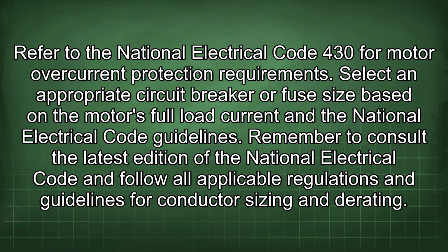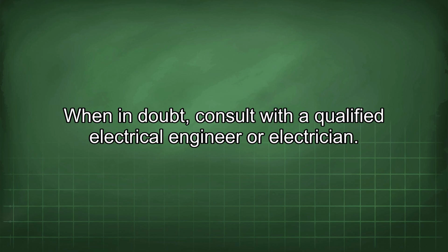Refer to the National Electrical Code 430 for motor overcurrent protection requirements. Select an appropriate circuit breaker or fuse size based on the motor's full load current and the National Electrical Code guidelines. Remember to consult the latest edition of the National Electrical Code and follow all applicable regulations and guidelines for conductor sizing and derating. When in doubt, consult with a qualified electrical engineer or electrician.